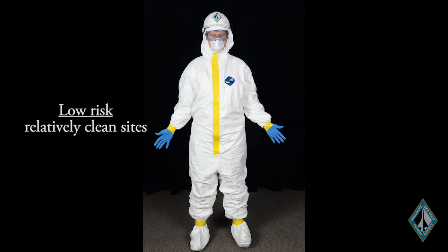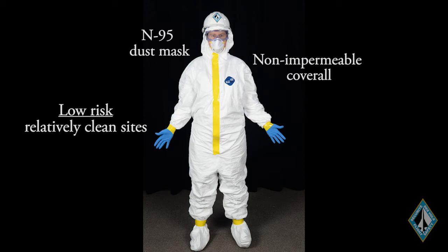Low-risk PPE is for relatively clean sites, such as intact aircraft interiors and hangar spaces, where there is little, if any, contamination and only nuisance dust. Non-impermeable coverall, N95 dust mask, nitrile glove, hard hat, boots with boot covers.